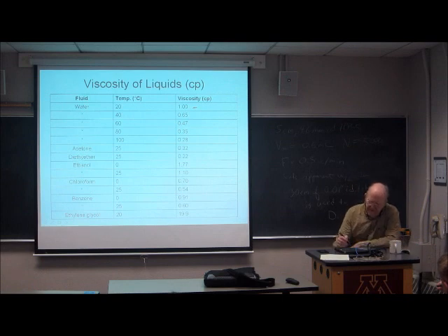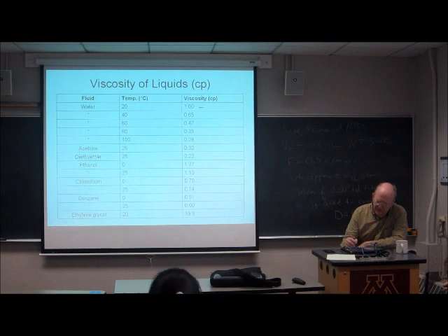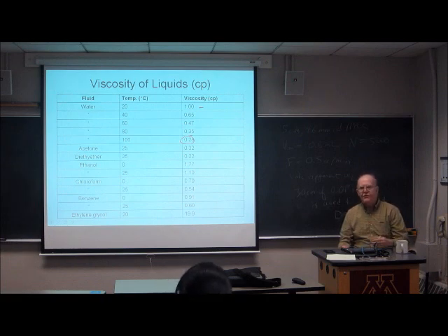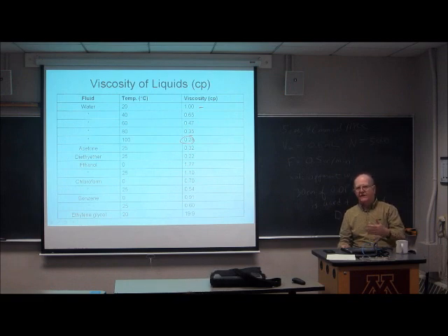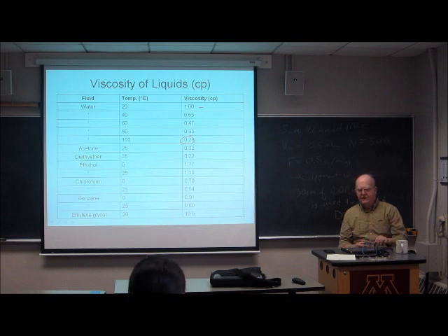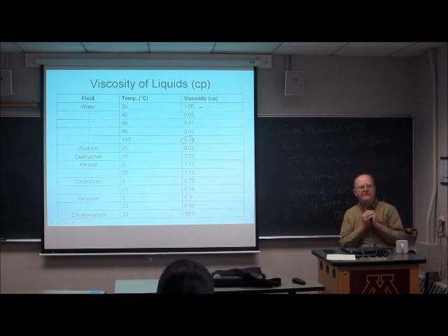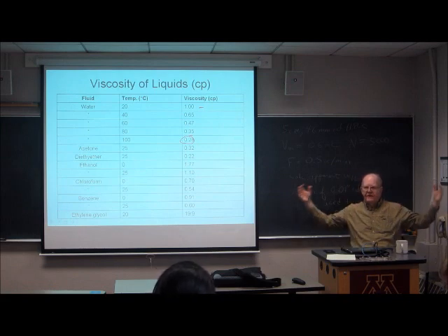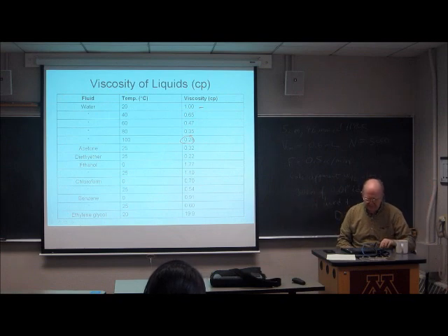Other interesting thing about liquids is their viscosities invariably get lower as you increase their temperature. And water at its boiling point, still liquid water, not the gaseous form, has a much, much higher viscosity than does gaseous water at the same temperature, because the density of the liquid phase is a lot higher than the density of the gas phase, so the molecules are a lot closer together. And there's a lot more interaction between the molecules when they're closer together than when they're in the gas state.